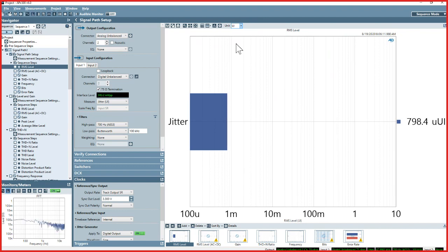We're measuring the digital interface itself, and now we're looking at the amplitude of the jitter that's coming in from this device. And this is where I was referring to an entire UI being quite a bit of jitter. The residual jitter of this analog to digital converter is less than 1 micro UI, or unit interval, which is sort of a sample rate independent view of jitter.